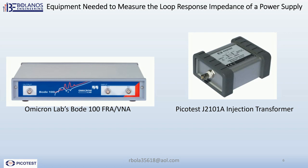Okay, the equipment that we need to measure the loop response is, in my case, I'm using the Omicron Lab Bode 100, which is a frequency response analyzer, and it's also a vector network analyzer. And I will be using an injection transformer, the Picotest J2101A. So those are the two pieces of measurement tools that I'll be using.